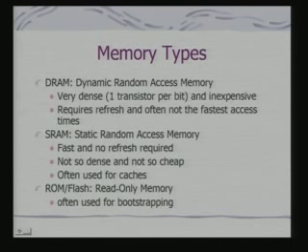Further, we can look at their divisions into dynamic RAM, DRAM, static RAM, that is SRAM, ROM or flash, which are read-only memory, and read-only is often used for bootstrapping. In fact, flash has some characteristics so that we can even do in-circuit writing as well. So they are not strictly read-only, but their primary usage in applications may be for read-only purposes.